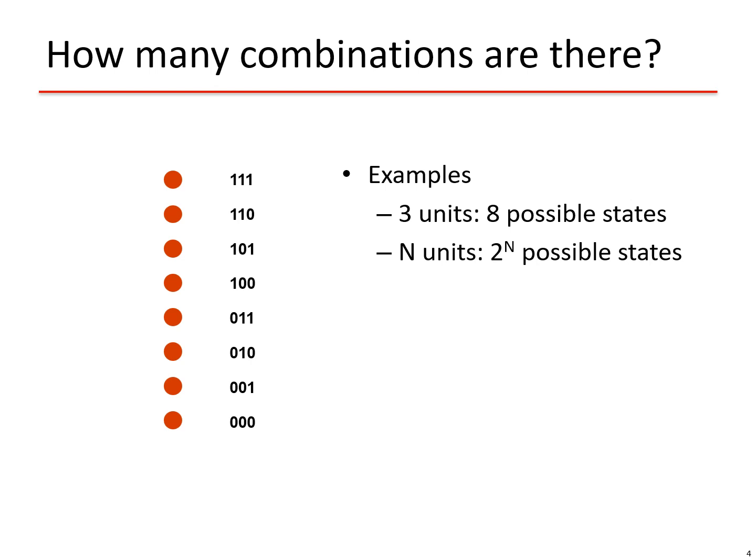In unit commitment, we create a combination of the possible states of those units which have to be kept in the on state or which will be used to supply the load. The combinations are usually written in binary form. Suppose there are n units in the system, then the total possible combinations or states will be 2 to the power n.